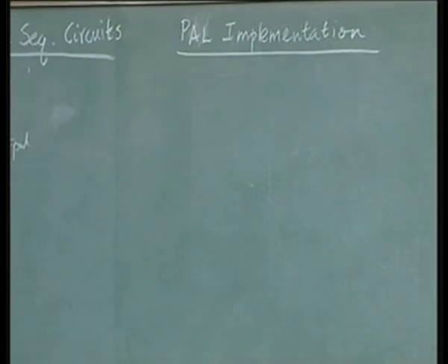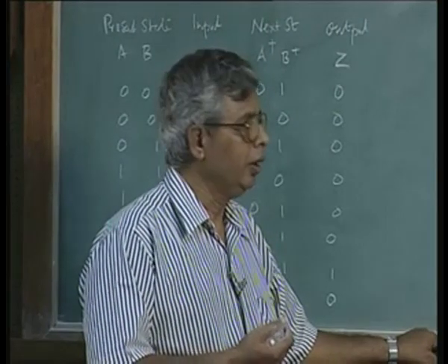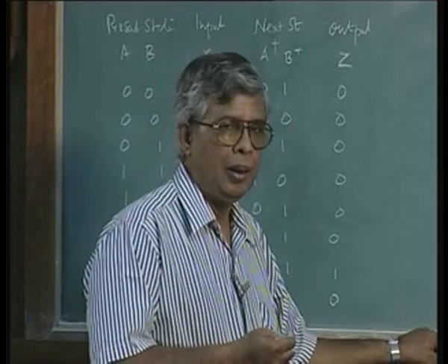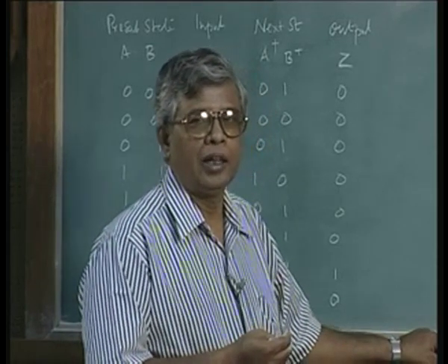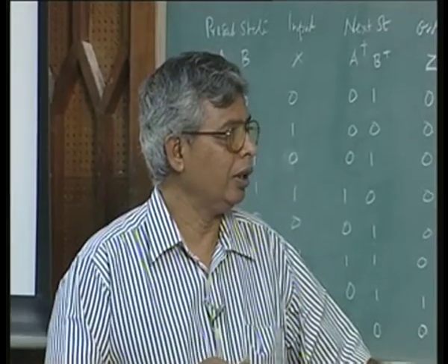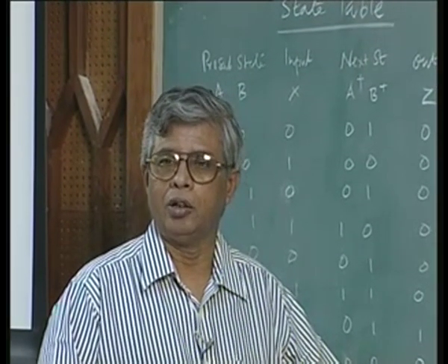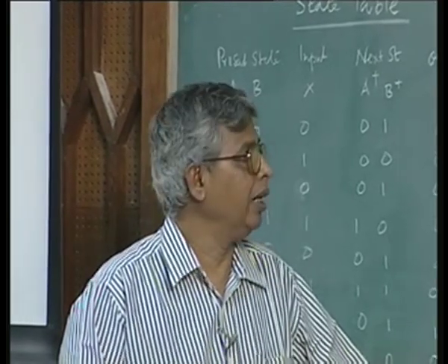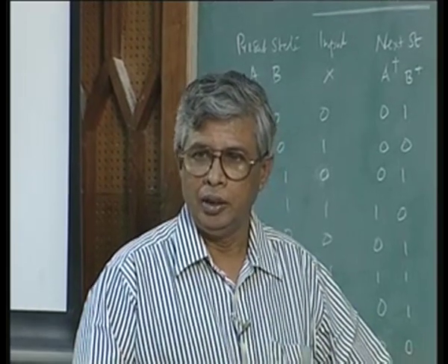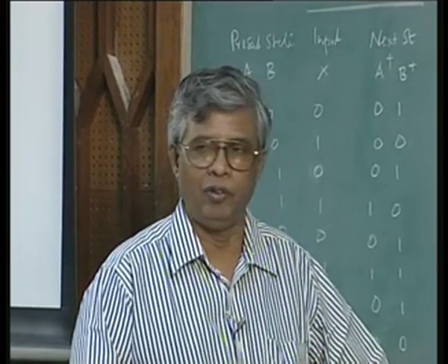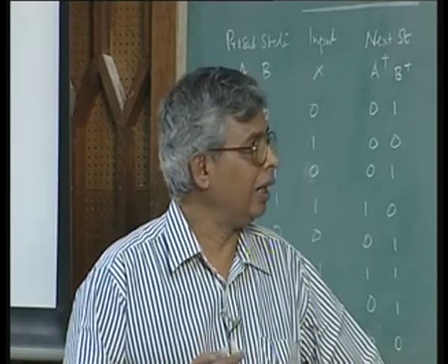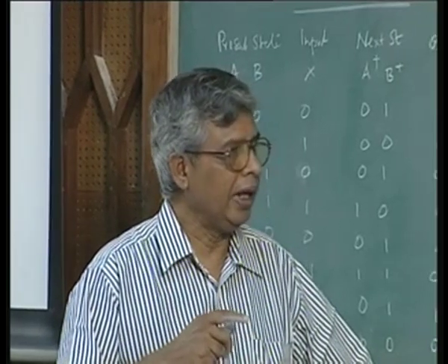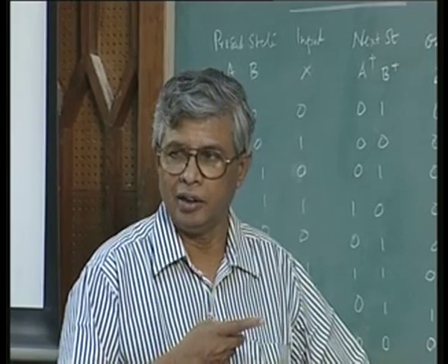Now can we integrate the flip flops also into the hardware? Yes, it is possible, because we have already seen these different versions of programmable logic devices, PLAs and PALs. These PALs also have registered outputs. We saw when we discussed PALs that it is possible to have programmable logic devices with registers in the output. That means the sequential circuit requirement of a flip-flop can also be built into the PAL. So, in a single PAL, I can now get the whole circuit, the combinational logic as well as the registers or flip-flops.